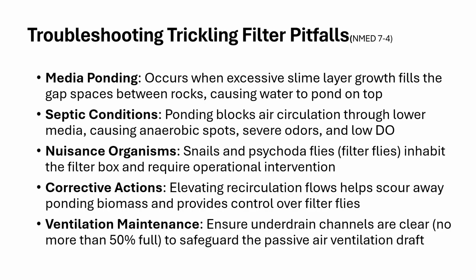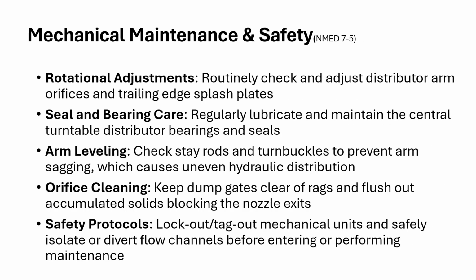Okay. So you should know this. But again, the big variable here, adjust recirculation rate. You can increase it or decrease it. Think about what you're trying to do. That'll tell you whether you want to increase or decrease the recirc rate. Okay. A few other things you can do. Well, on maintenance, I'm sorry. So we're now going to switch from troubleshooting to maintenance. So you want to check that distributor arm.